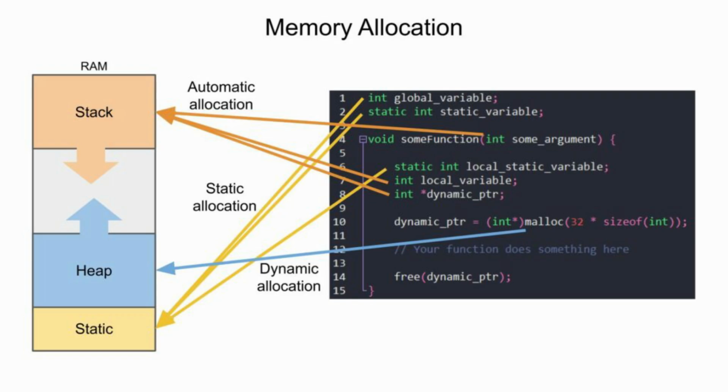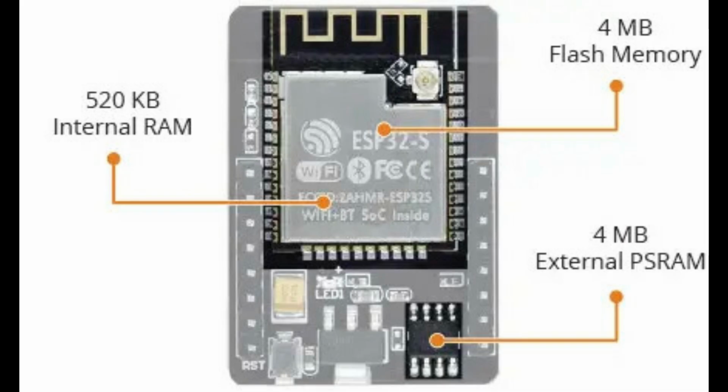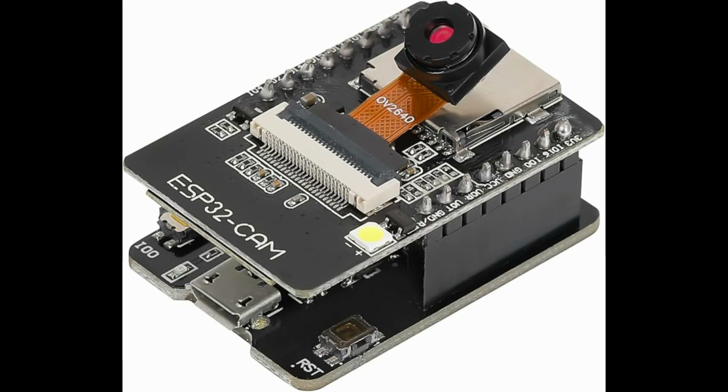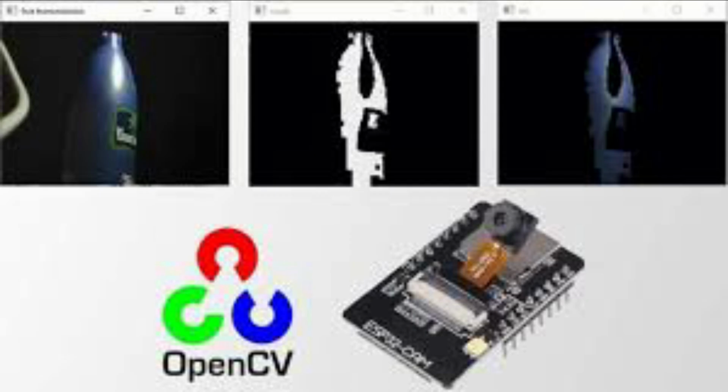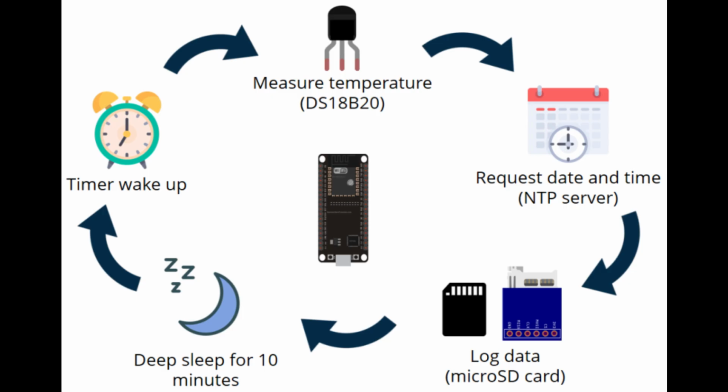Flash memory is used to store whatever firmware we write. Next, whether you need PSRAM or not. This is used for camera and image processing and buffering large data in your application. If you have these cases, then you want to move to a PSRAM chipset.